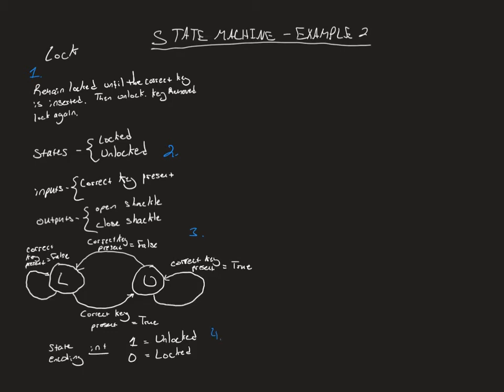Now the only thing left to do is program it. So on the right you'll see our 2 rails, the left rail being the positive rail and the right rail being the negative rail, that you usually see in a ladder editor. So at the top we're going to have our state transition logic. So before you ever worry about outputs, worry about controlling the state transitions.